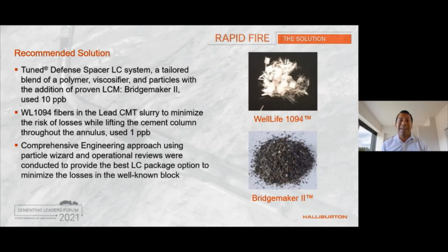So, due to the severe nature and the costly impact of not reaching the top of cement, we wanted to be as aggressive as possible with this LCM package, but we made sure to perform lab tests with the LCM concentrations chosen to minimize any issue with mixing and pumping LCM in both the spacer and the cement while pumping the cement job.